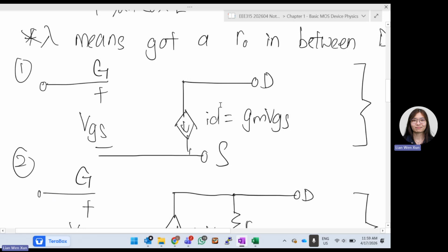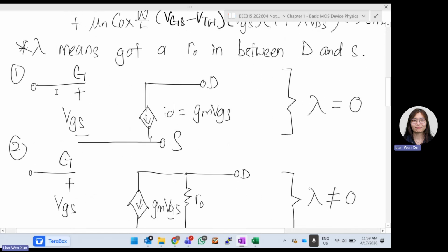The current that's flowing, we call it gm·VGS. Which means that my VGS is controlling how much current flows, depending on gm. That's why this current is called gm·VGS all the time. And then here is just VGS. Here is open. The gate and source is open, so we call this VGS. Okay, this is the ideal case, where there's no channel length modulation, no body effect or anything.